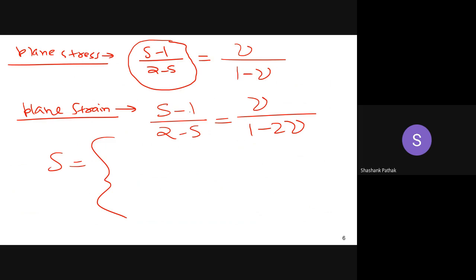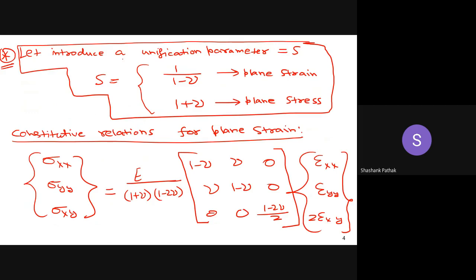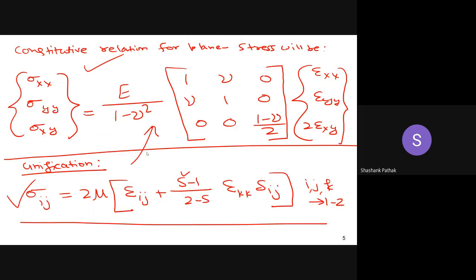So basically you got this parameter for plane stress and plane strain, and if you put that parameter in this unified constitutive equation for plane stress and plane strain, accordingly you will get either this one or this one. So that's how, using the parameter S, you can unify the plane elasticity problems, the plane strain and plane stress problems.